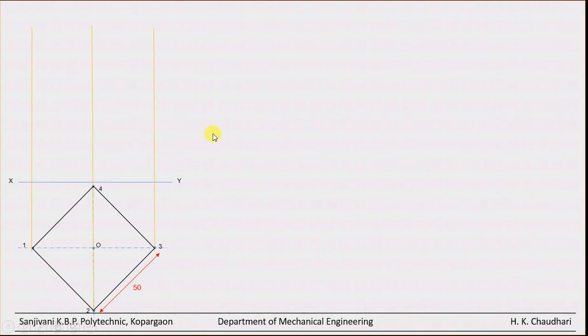projections. Now see the height of the prism is given 90 mm. So measuring 90 mm from this XY line, draw the projection or the locus of the top surface, top face. Now these two rectangular parts are shown here. They represent the rectangular faces 1, 2 and 2, 3, clear. So for better understanding, give the labels.